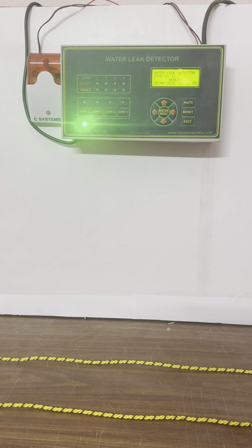Now zone 2 is in disabled condition. I am going to enable zone 2, but without connecting the sensor cable, or when the sensor cable is open, you will be able to get the fault indication. I am going to demonstrate it. I am just going to enable the